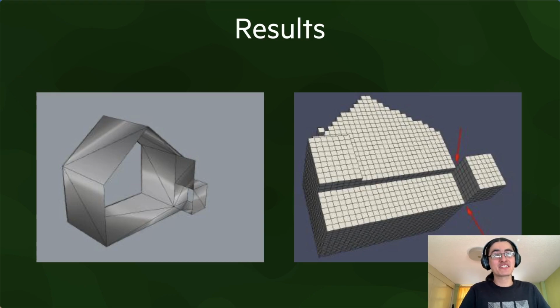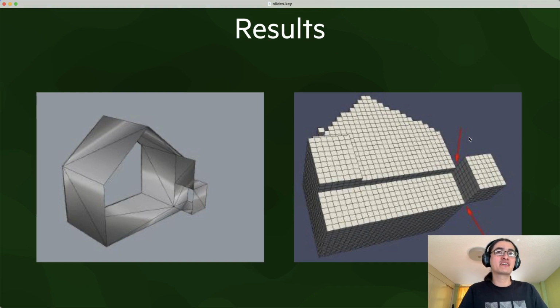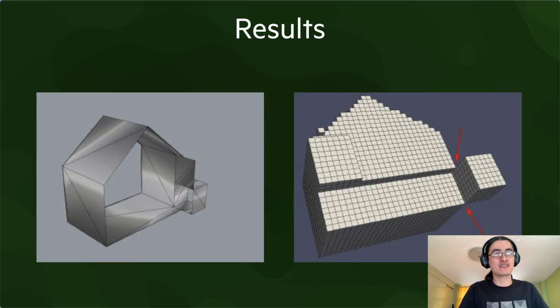Also, in some 3D city models, namely the one of Rotterdam, when you have row houses, the city of Rotterdam actually doesn't put walls between the houses, so you only have this ring shape that goes around the visible part plus the bottom of the house. It's not perfect, but Damien's algorithm can recover a bit from that. Although in some cases you can end up with things like this, non-manifold edges, which might be a problem when you try to reconstruct a mesh from that.